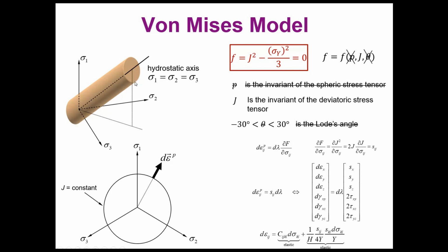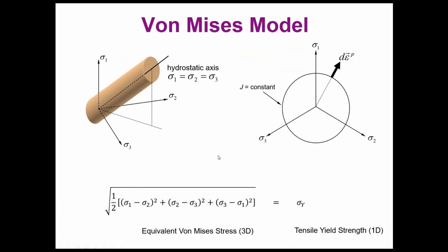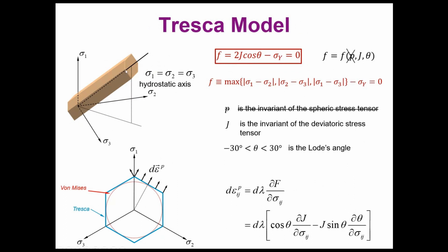But if you add caps, you are adding a condition to study the possibility of failure under hydrostatic stress states. If not, you don't have any limits. So initially, the model is not looking for failure under loads that produce a hydrostatic state of stresses.